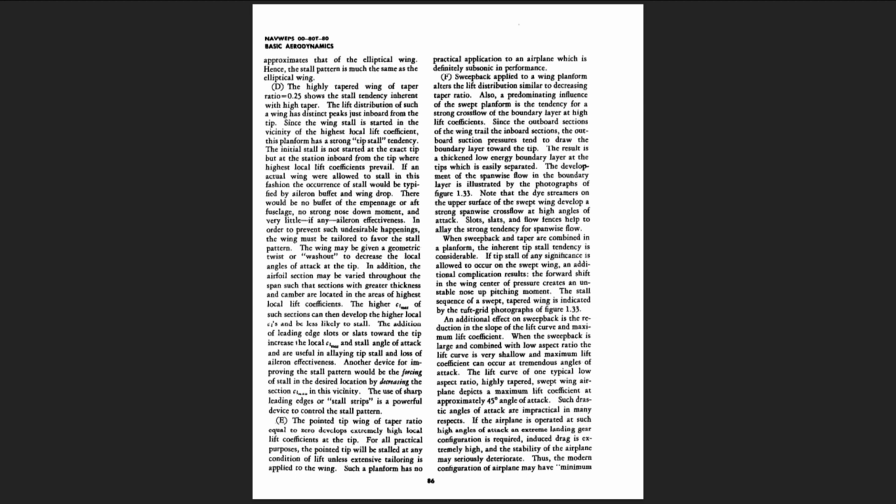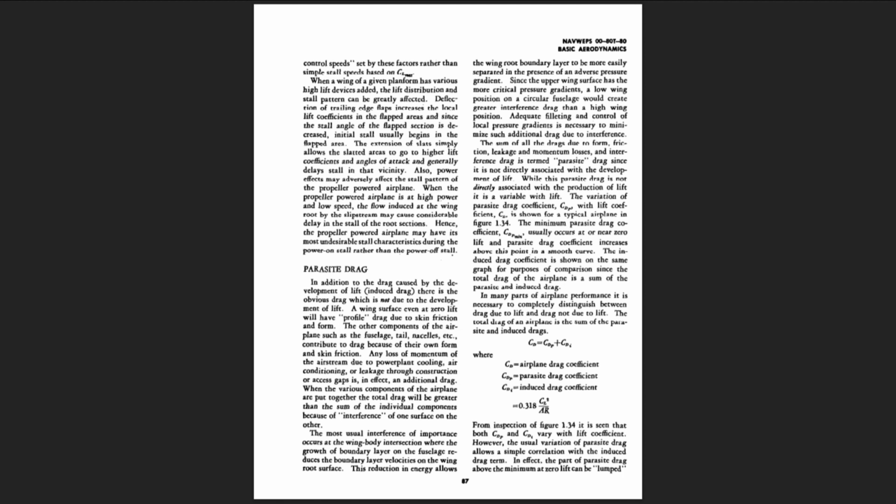Such drastic angles of attack are impractical in many respects. If the airplane is operated at such high angles of attack, an extreme landing gear configuration is required, induced drag is extremely high, and the stability of the airplane may seriously deteriorate. Thus, the modern configuration of airplane may have minimum control speeds set by these factors rather than simple stall speeds based on CL max.